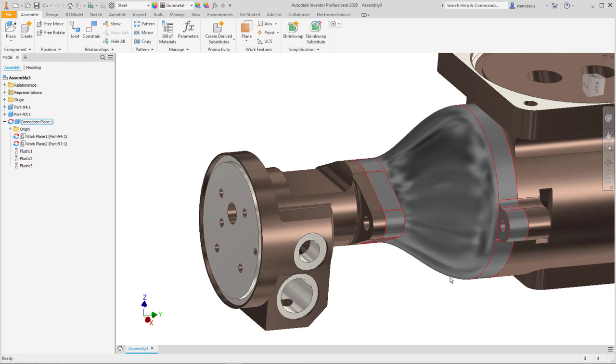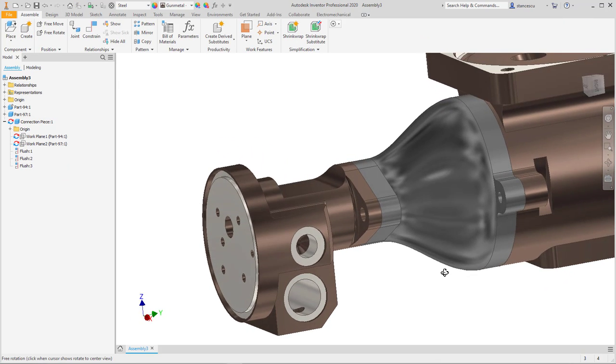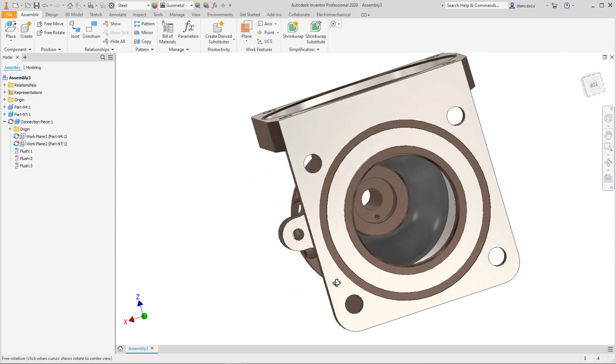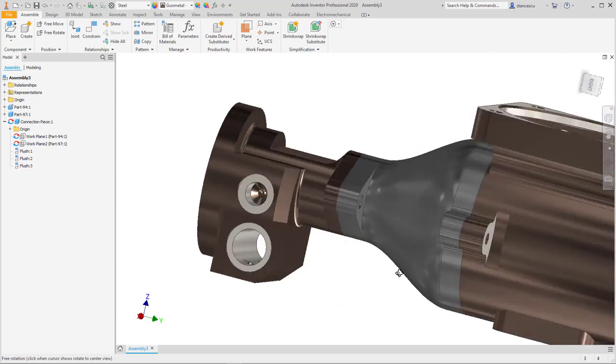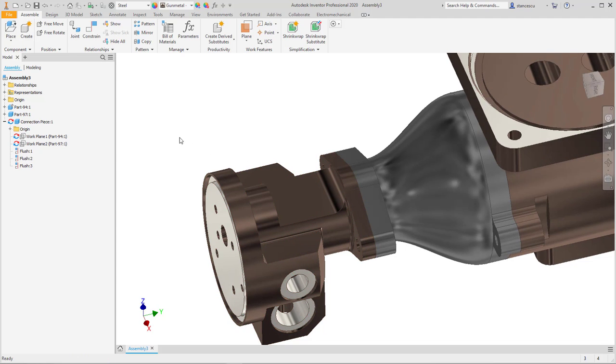Return, and now I can change something. Very fine thing to change is this distance of 80 millimeters. I only selected this constraint, and I write here, say 60 instead of 80, and please look to this, what happens when I tap enter.